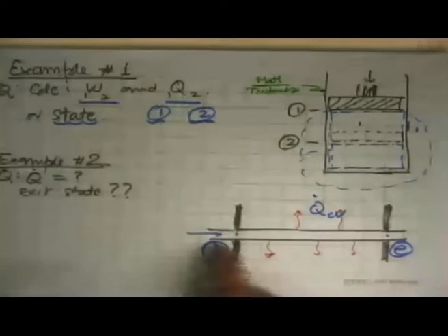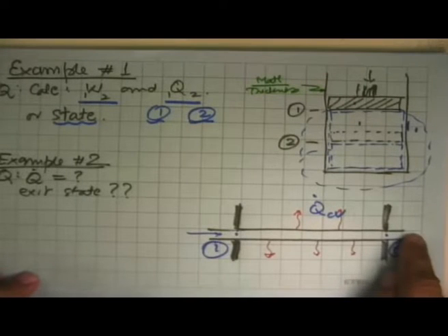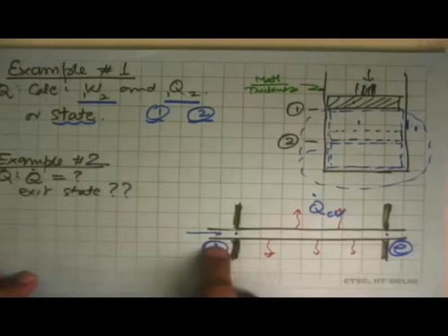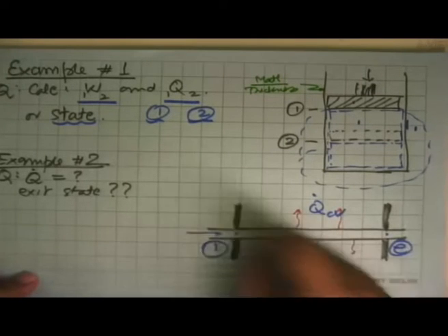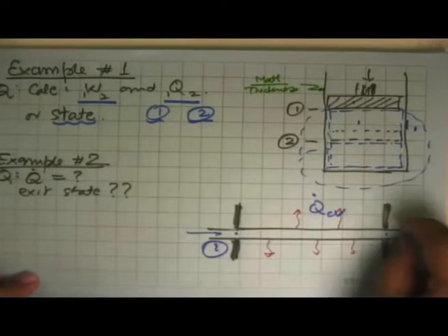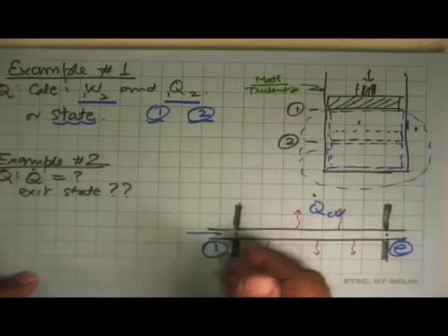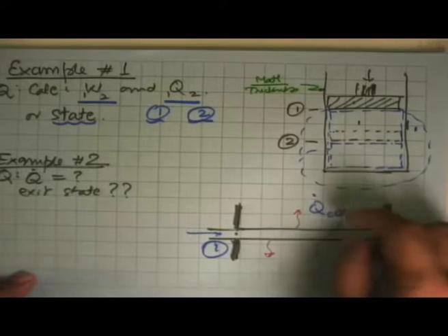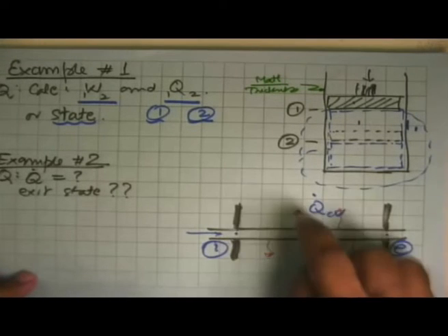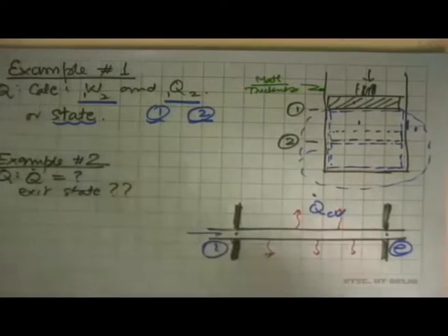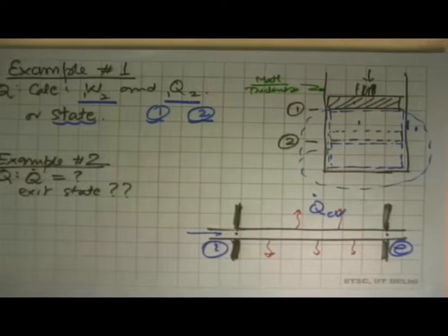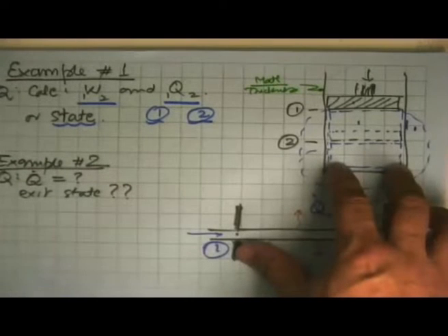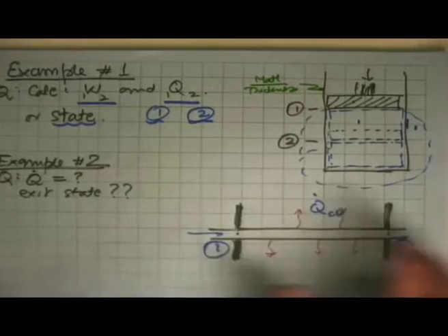So here also we get the same thing. If we know the state that it is going to be here, we say, look, this is the inlet pressure and temperature, this is the outlet pressure and temperature. We have to select a tube which will not rupture at the highest possible pressure or temperature. And so let's see what materials we can take. What are those materials which are compatible with this substance, and within that, how thick should it be, and all those decisions start to come in. So what I'm trying to say is that the basic thermodynamic calculation is the starting point for the entire mechanical design of the application.